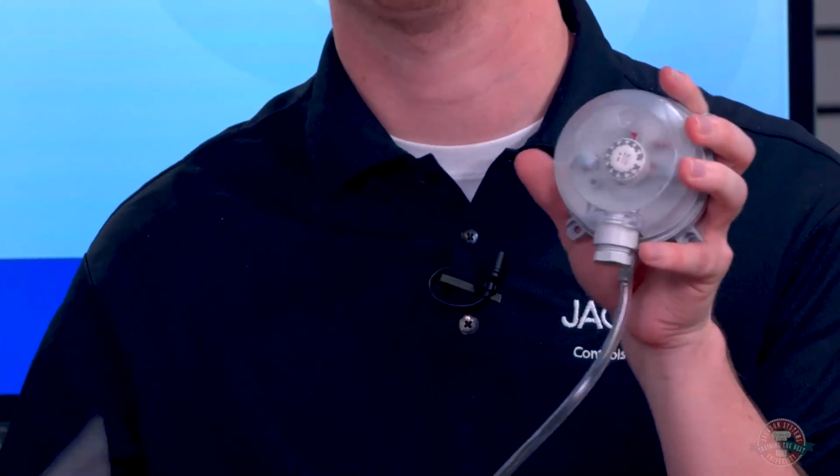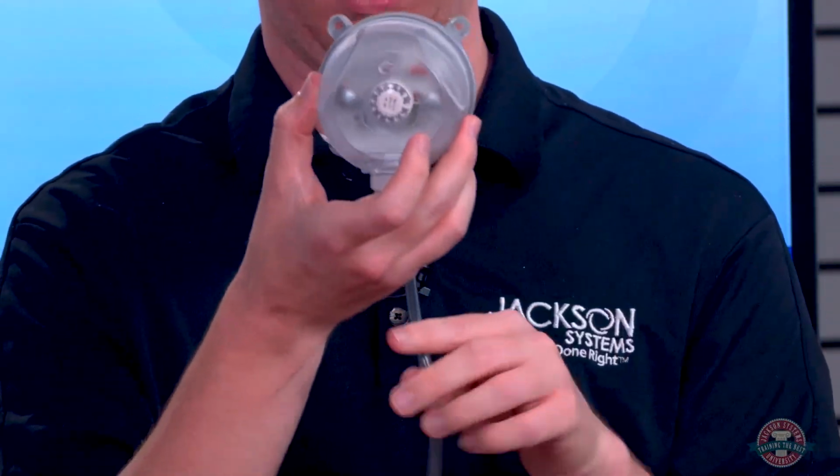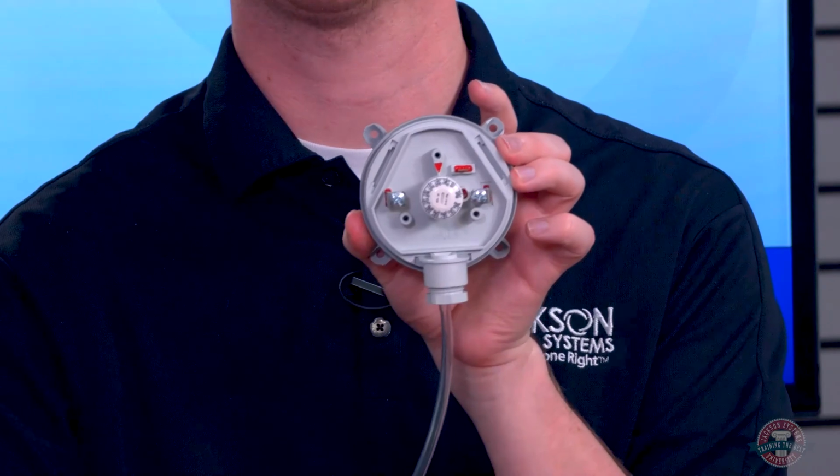All right. Then our final question was just going real quickly back to the ESP. So how do you, again, adjust the static pressure? Oh, there's one right up there. So the question is, how do you adjust the static pressure on an ESP panel? Each ESP panel, if it has ESP in the part number, ships with one of these. So you would just mount this on the ductwork most of the time. You would put this in the supply ductwork. It comes with all the poly tube and the probe, and that just slides right off.